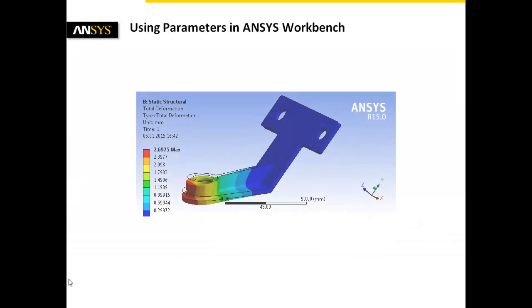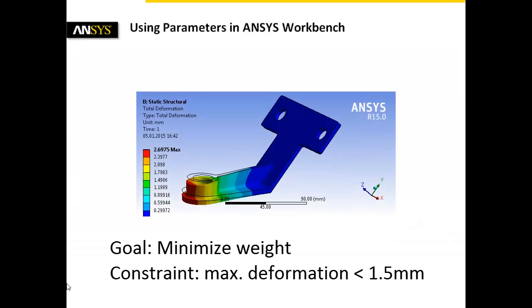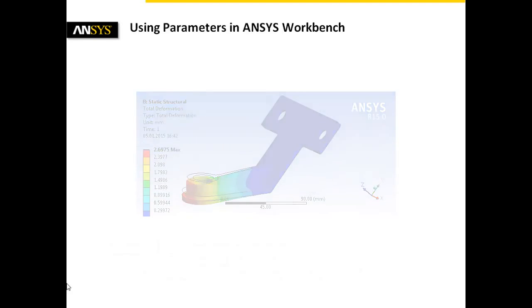The design goal is to minimize the weight by varying geometry parameters, while the maximum deformation should not exceed 1.5 mm to meet tight tolerances. Let's take a look at the process of parameterization.